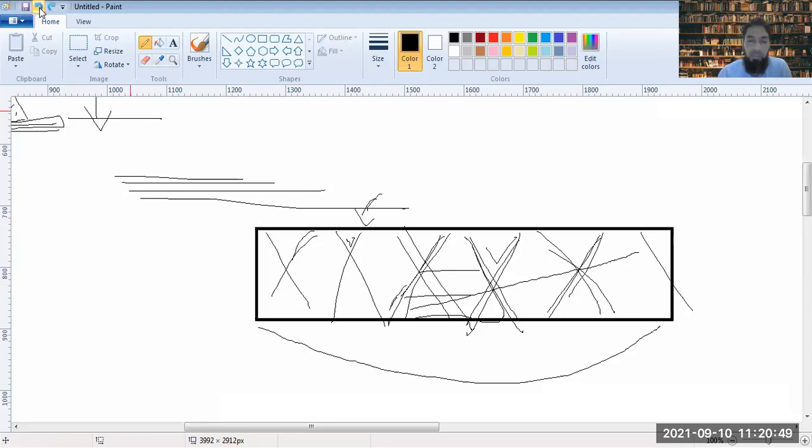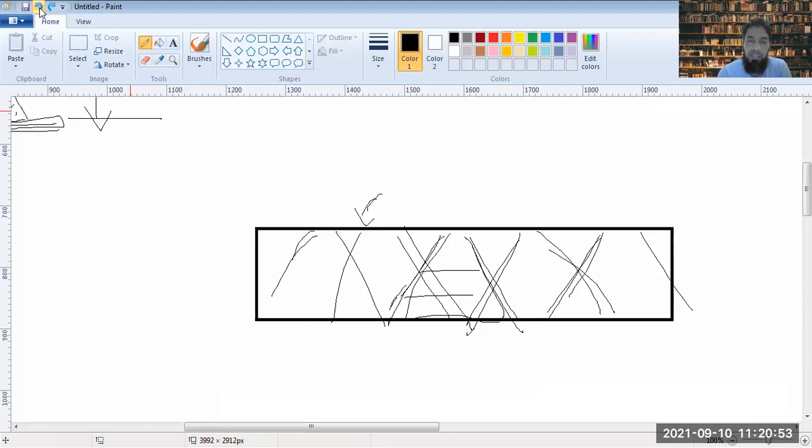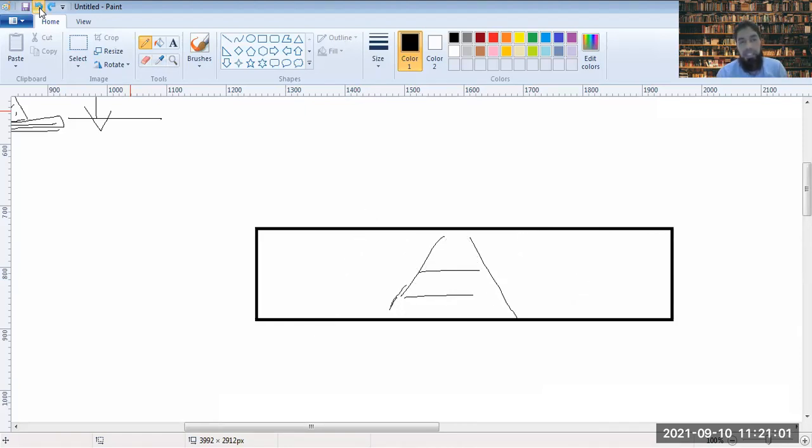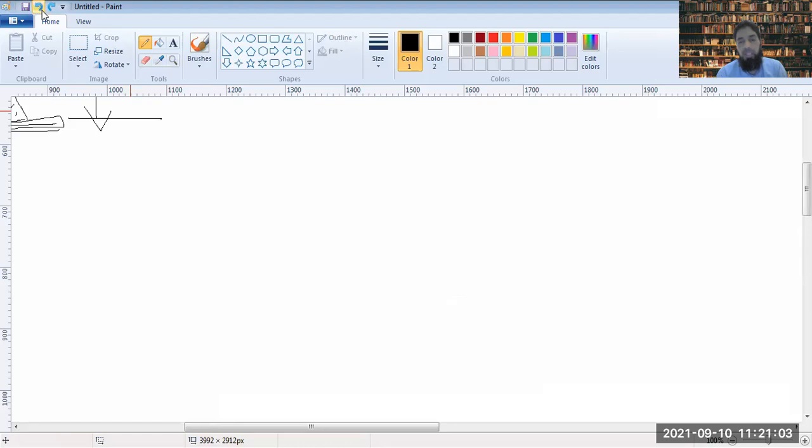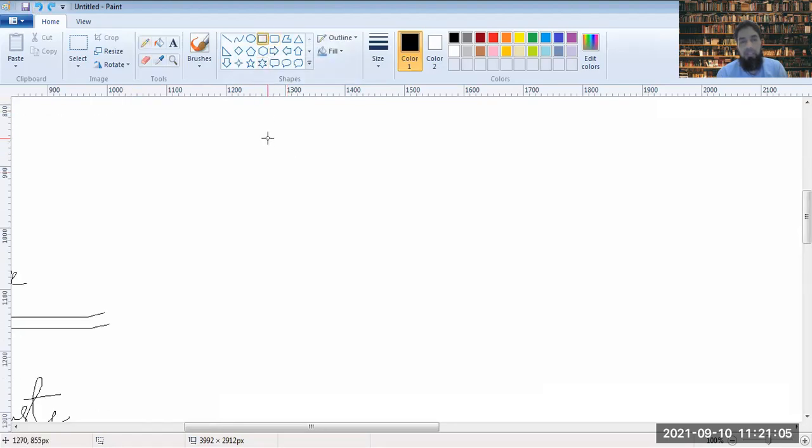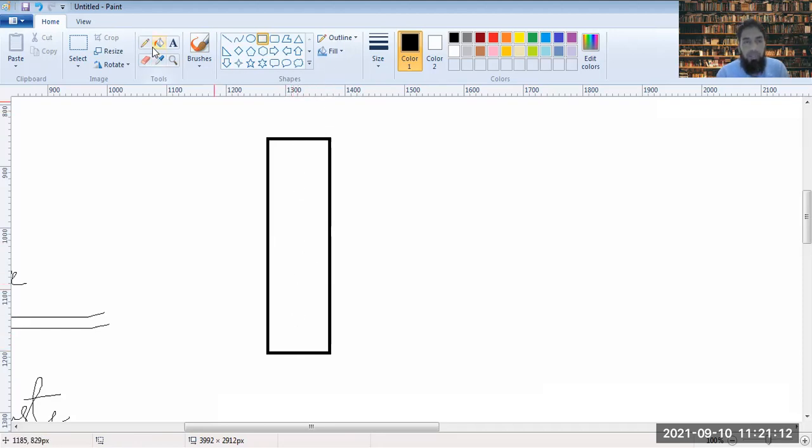So there are various things to be noted down why we require particular slump values in particular situations. Similarly, in the case of columns where we are using high slump value, one of the dimensions is quite less. This dimension is quite less, this dimension is quite less, and this dimension is quite big.